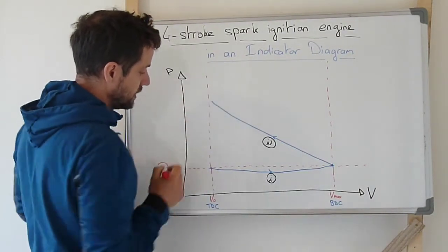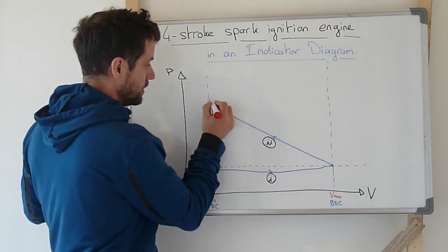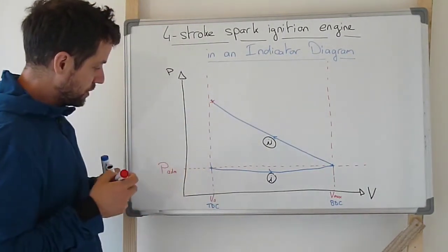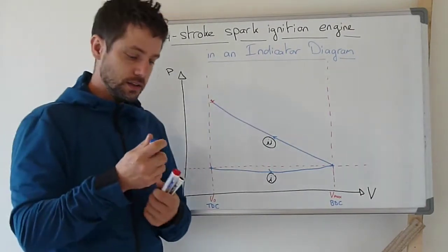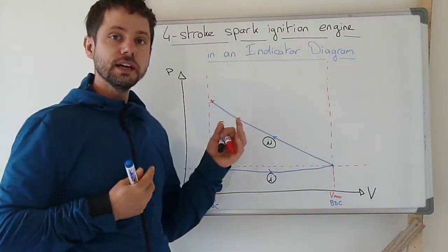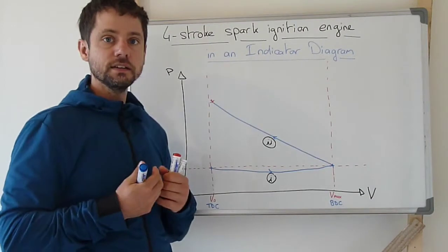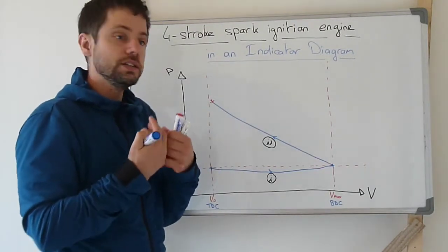That's why I stopped here the curve just before the top dead center. That's what we call the advance of the ignition.